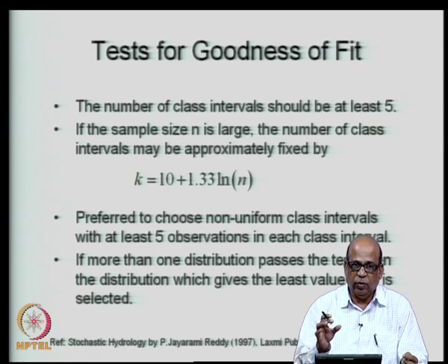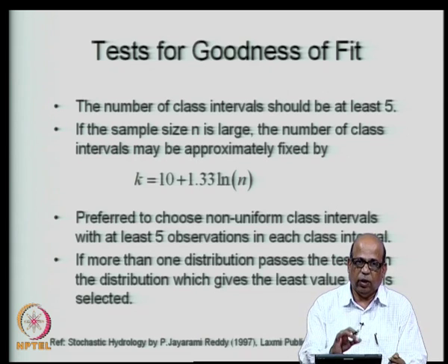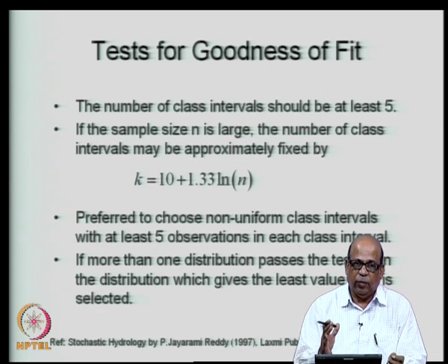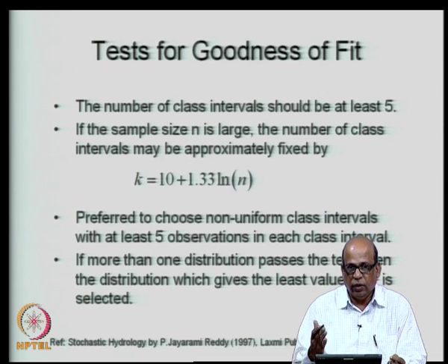Then there may be many class intervals which are not represented at all, in which case you may have to combine them and bring it down to 5 or 3 class intervals. For these tests to be more reliable, the available data must be large in length. If you use this test for just 10 values, 20 values and so on, then your confidence in the results can be quite small, and therefore any statistical tests of this type, looking at goodness of fit of distributions, must essentially be done on large length of data.